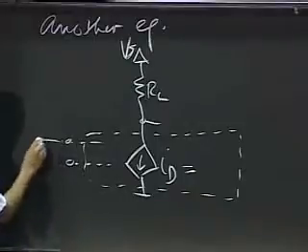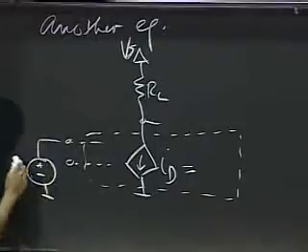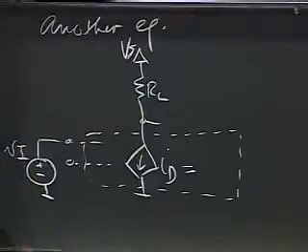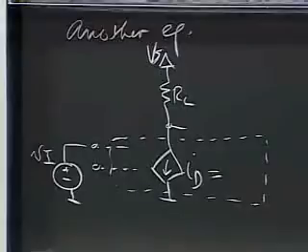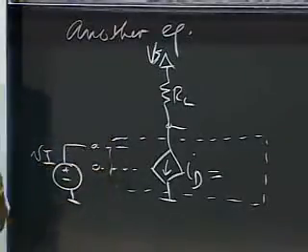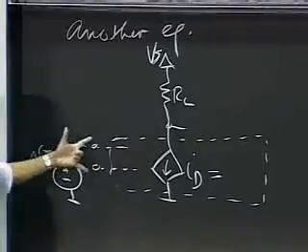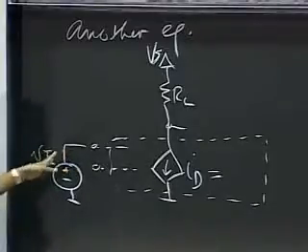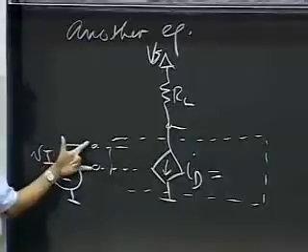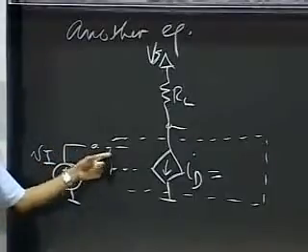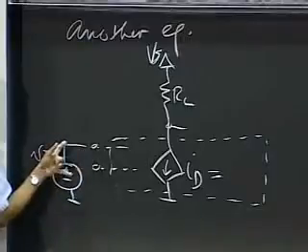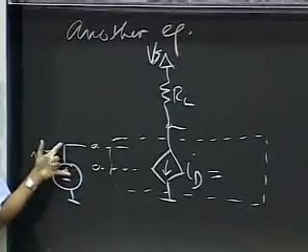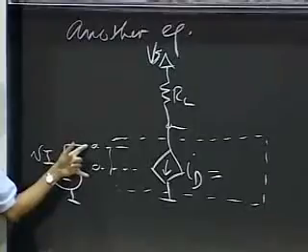And let us say that I apply some voltage VI to the input port. The reason we often don't show the input port is for many practical dependent sources, the input has no other effect on the circuit. So for example, in this case, the input has infinite resistance looking in. So therefore, if I apply a VI here, it doesn't draw any current from VI. I simply apply the voltage VI.